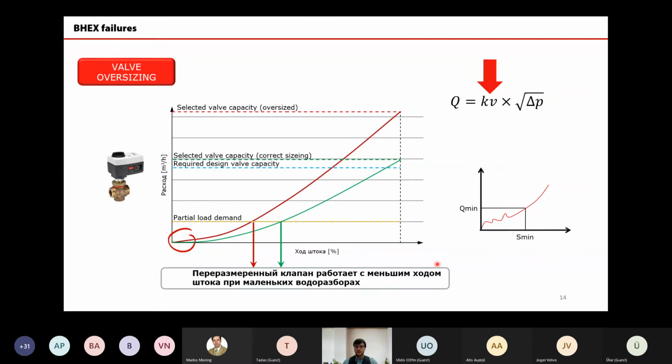Why is it so? Because we have accumulated effects of a couple of things. First, in many cases, the valve design might not be done in the very correct way. So that means, as I was explaining to you before, either I'm working with a much lower real capacity than I designed my valve for, or I'm working with a huge surface margin of the heat exchanger.